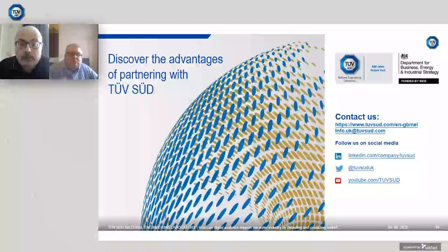In the webinar, you mentioned case studies looking at Coriolis and ultrasonic meters. Have you undertaken any work on electromagnetic meters? We've undertaken a huge amount of work on electromagnetic flow meters in the past, but what we will need to do is undertake some baseline testing in order to characterise the differences between the electromagnetic diagnostic data that's generated and those that are generated with Coriolis and ultrasonic flow meters.